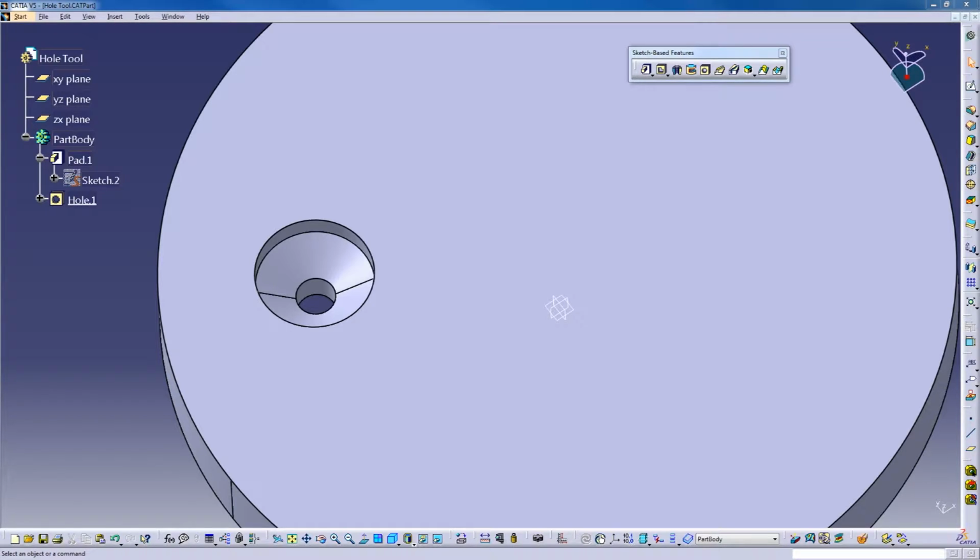And so then what you find out is things like, well, I can make a hole for this fastener, but I need to make sure that there's an actual fastener that's going to go in here. And you could look at the data sheets for sure, or you could look at the rough idea of it. You could say that it's an M5 countersunk, maybe 10 millimeter long fastener, and you could go off of that. But I would suggest that you actually go feel it, touch it, see where it comes from. Each manufacturer might have a couple of things about it that are a little bit different.